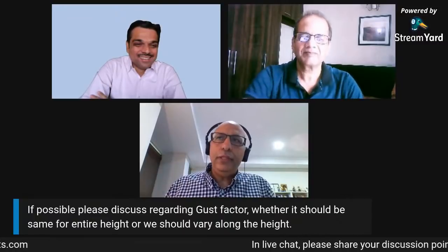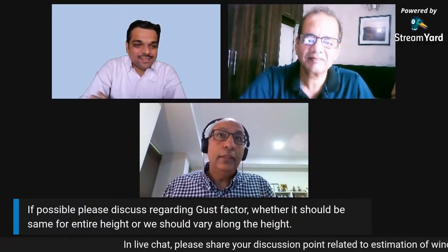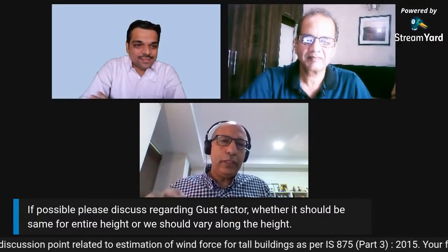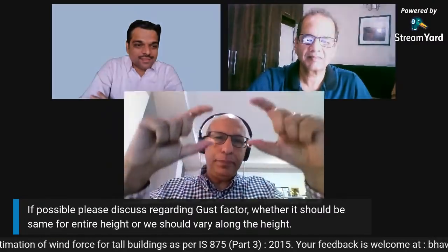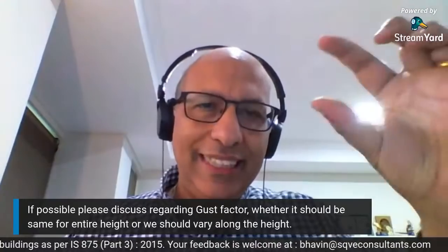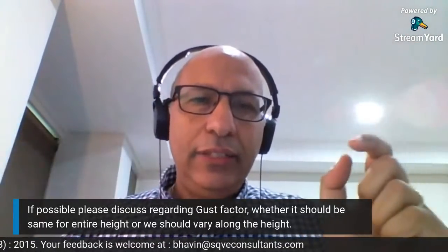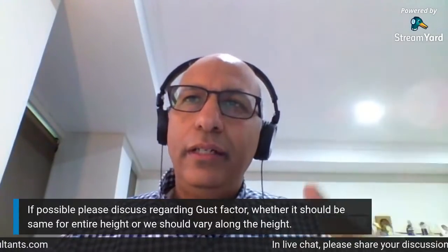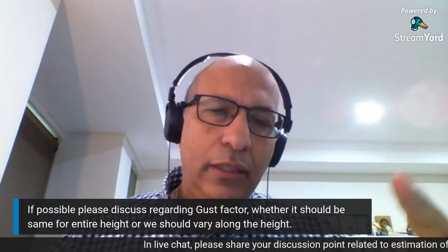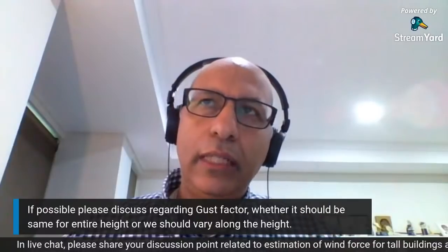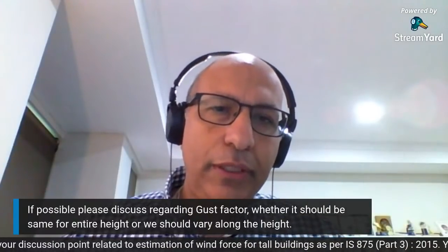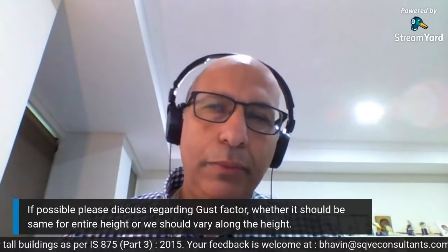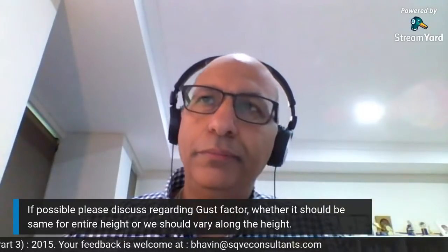Okay. So if you follow the exact letter of the Indian code, for the along wind, you need to break up the tower into sections. Each section needs its own gust factor to be calculated for that area. Yes, it varies, but you will find that over the height, the variation in the capital G gust factor won't be very different, but there will be some variation as you go up, and it'll be slightly increasing as you go above the ground. The formulation is like that.